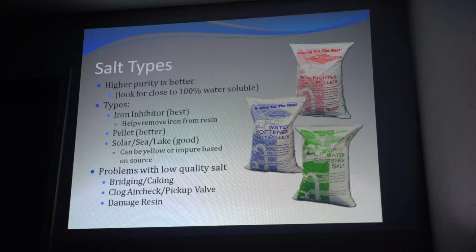Problems with low quality salt? Bridging and caking, clogged air checks, and clogged pickup valves. And you can also damage resin. You think, well, how can dirt damage resin? The dirt doesn't. The dirt in the salt is just going to cause problems with the control and plugging your brine tank if you use rock salt. It's not going to hurt the resin.